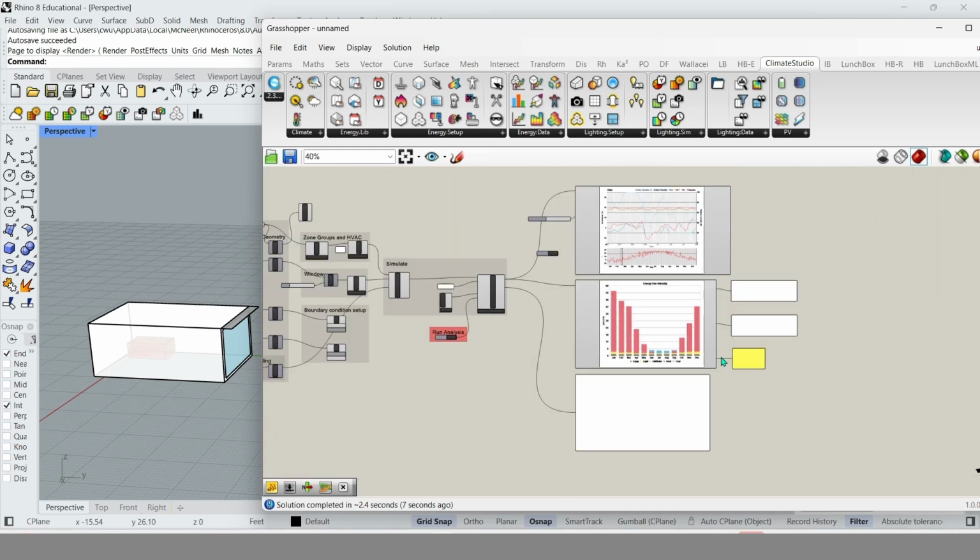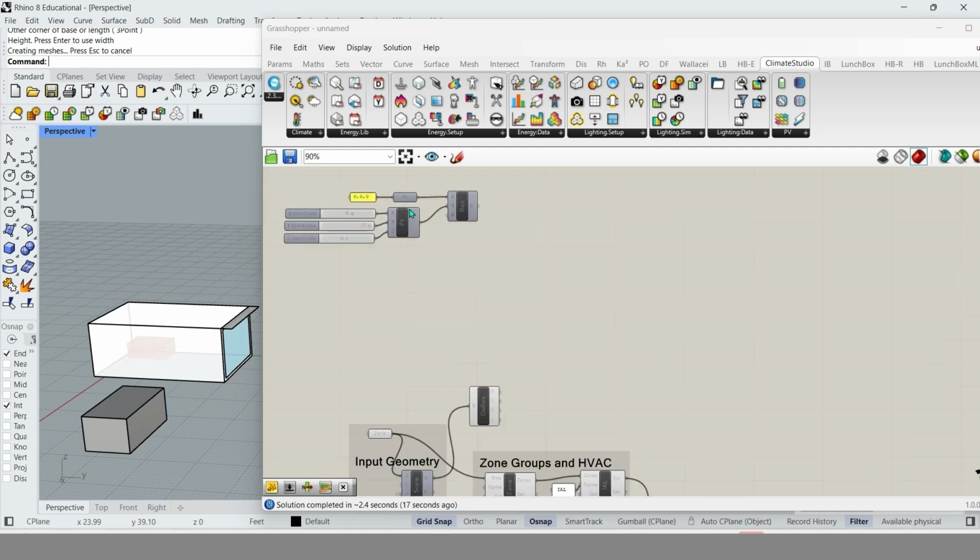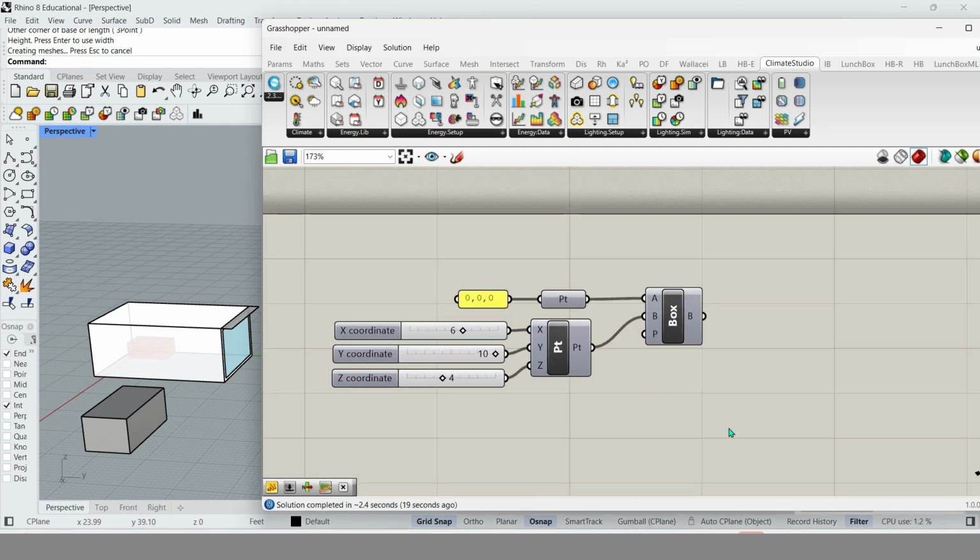My recommendation is that you keep the unit system consistent for the document setting, the input geometries in Rhino if you have any, and the geometries in Grasshopper. Always model them in the same unit system, and you can skip the unit conversion battery, and you are less likely to make mistakes.